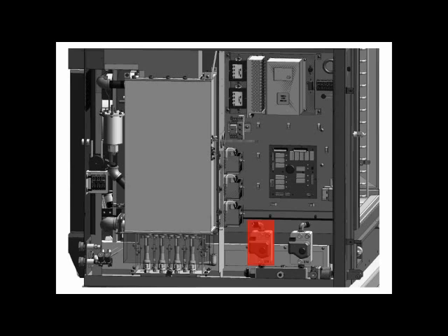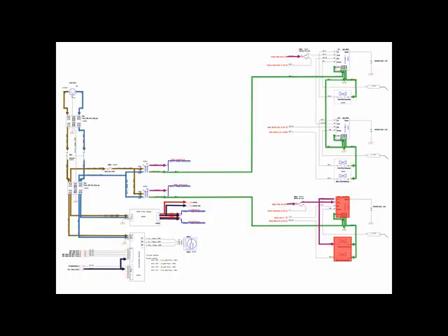The boiler gas valve is on the left of the gas manifold. The 24 volts to the pilot solenoid triggers gas to be sent to the boiler pilot assembly. At the same time the PV output was started, the spark was sent on the ignition wire to the igniter at the pilot assembly.